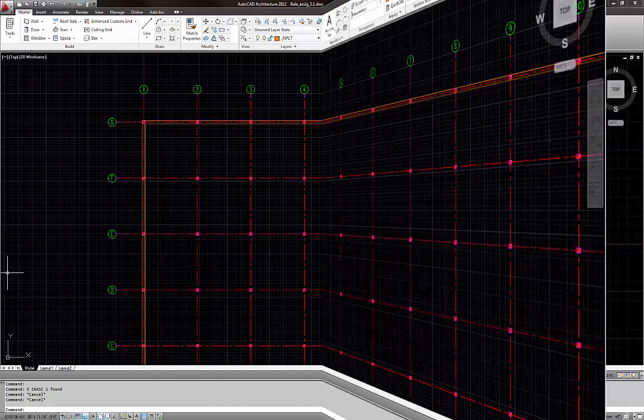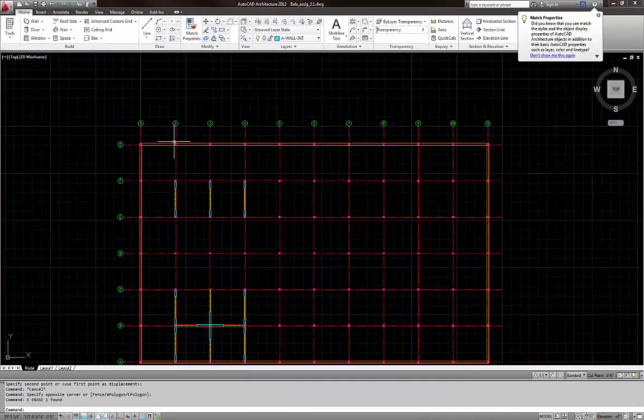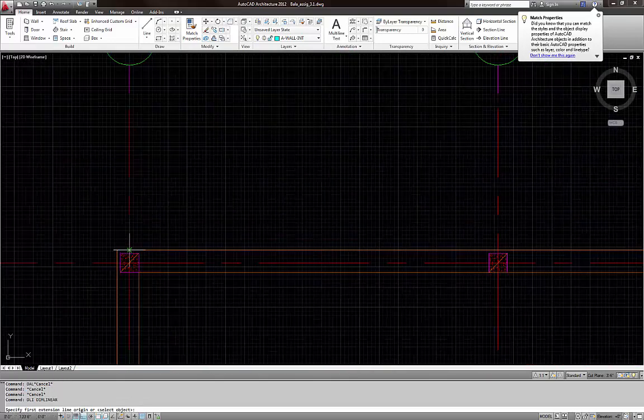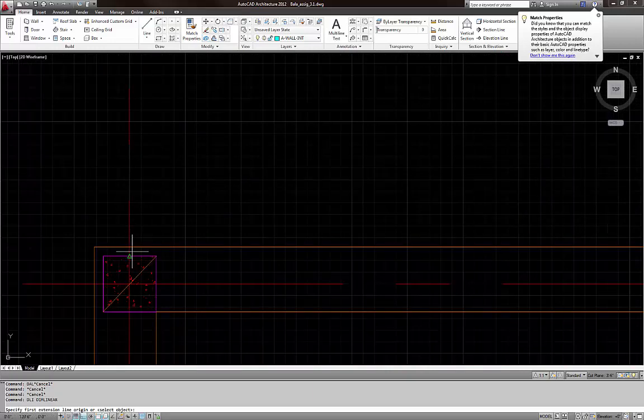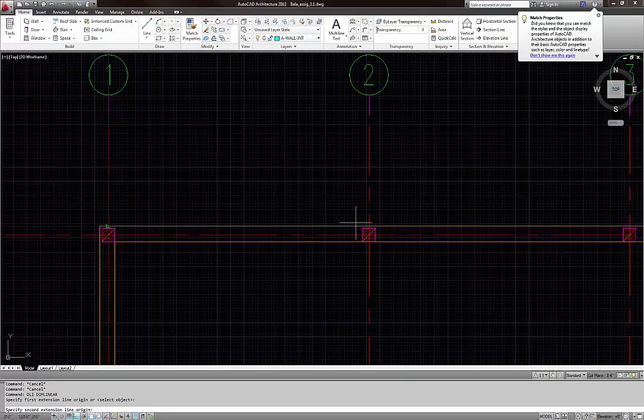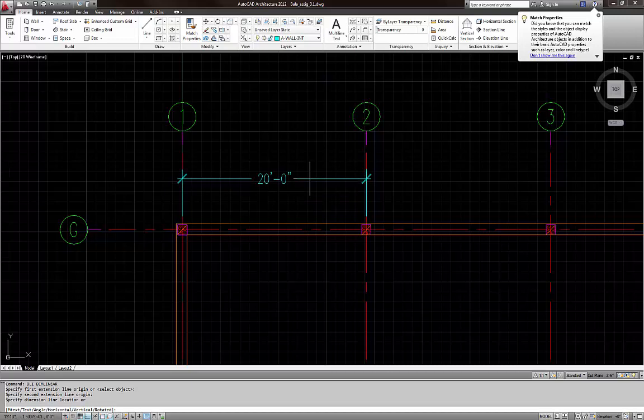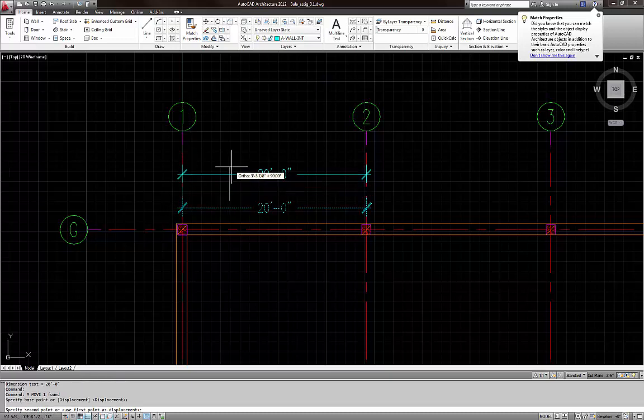And also if you look at this, now DLI for dimension, DLI, enter. I will click on this column, the center line, and to this center line, go up like this. Since it is 96, I'm going to put 96 divided by 3, enter. So that will give me a good spot. Then I want to move it up.